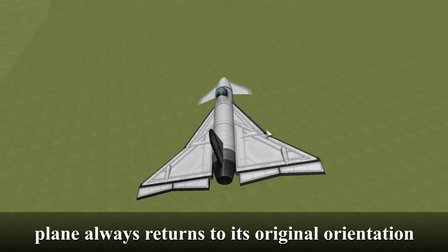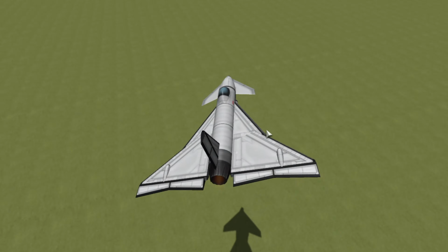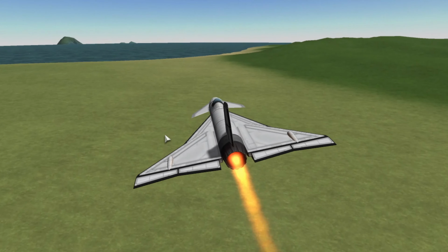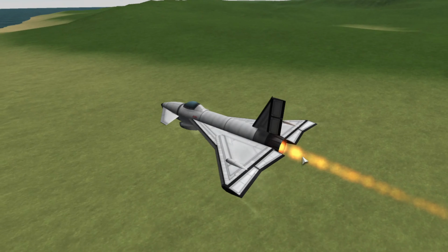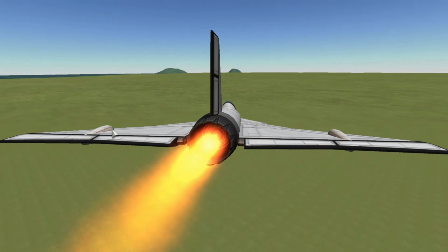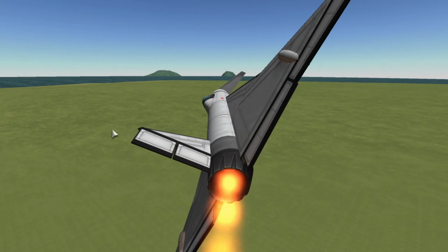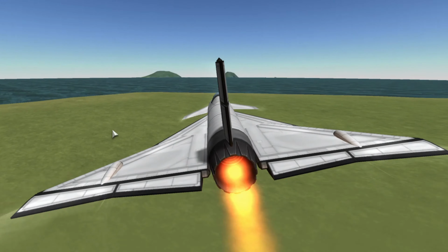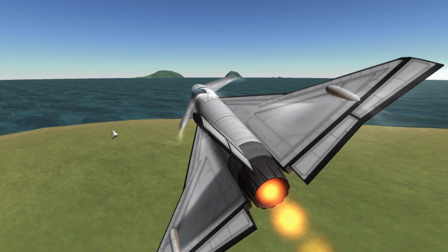Symmetrical airfoils are most commonly used as the vertical stabilizers on the back of planes. Their job is to prevent the plane from side slipping, which is when the nose of the plane starts to move to the left or right. Occasionally, they are used on the sides of rockets to keep them stable during flight. For example, the Saturn V had symmetrical airfoils on its side, although the Saturn V symmetrical airfoils also had flaps to make the airfoils unsymmetrical if need be. The flaps on airfoils are used to make them unsymmetrical or switch the direction that the wings are unsymmetrical in so that they produce a lift in a different direction.